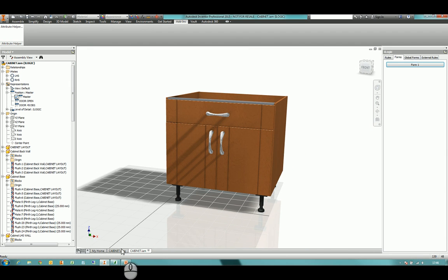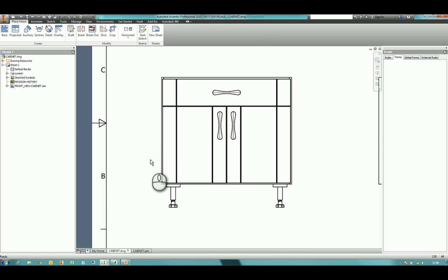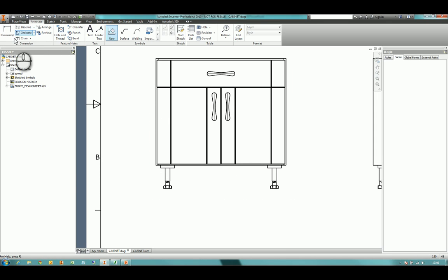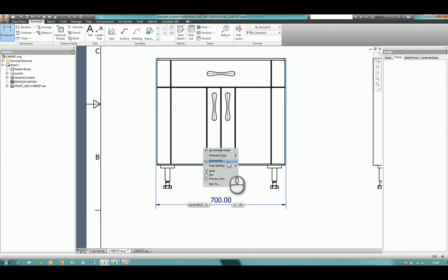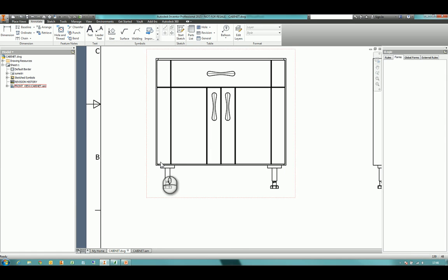Well, let's have a look at our drawing, and we'll start off by adding the dimension from there to here. So if you imagine adding a dimension manually, the way that we do this is I would select one edge, select a separate edge, and then select a position to place it, and I can decide whether it's a horizontal or a vertical dimension. There might be different types that we're placing. We have the same abilities within iLogic.